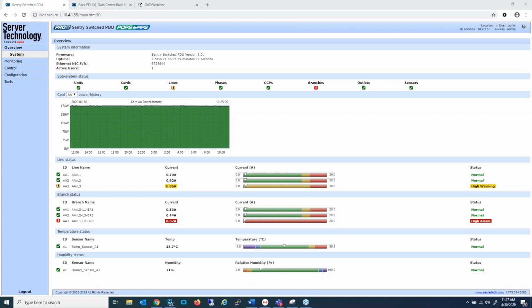So if your lines are out of balance more than 20%, we have the ability to notify you of that. It's effectively what you just described. That neutral conductor being out of balance results in current occurring on the neutral, which, if possible, all depending upon your equipment, you could balance those connections better, moving power cords around. If you get that down to 0, you're more efficient.